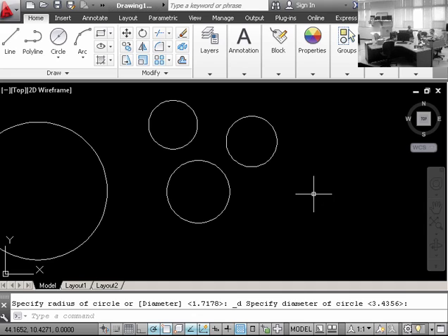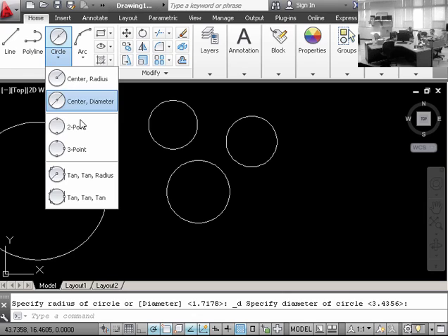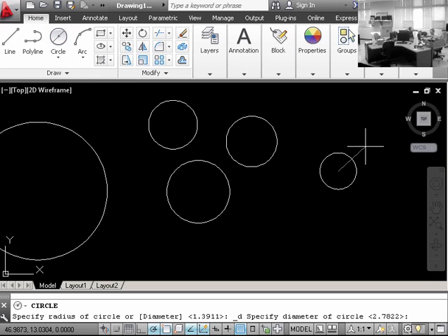Now you can freehand drawings, or you can just type them in. For example, I hit my circle diameter tool here, click a point, and let's pick a diameter, let's say 2.75. We just type it in, bam, there's a 2.75 diameter.